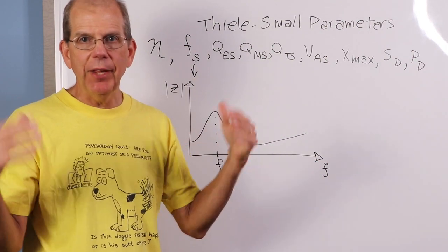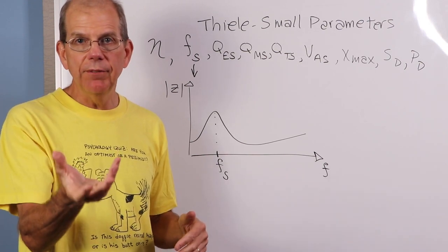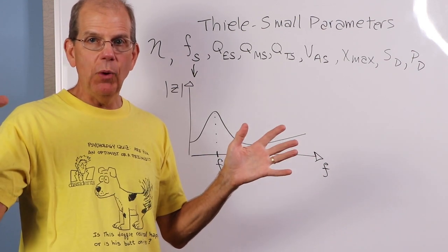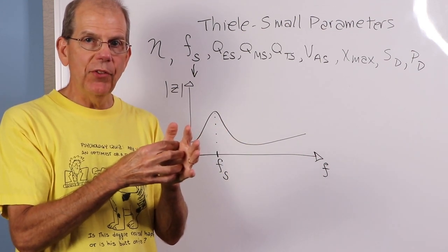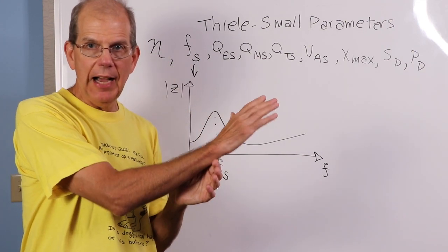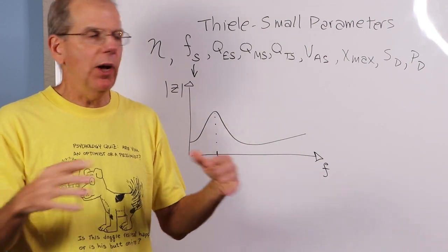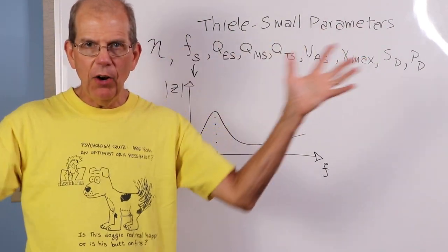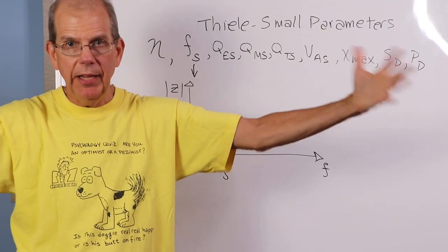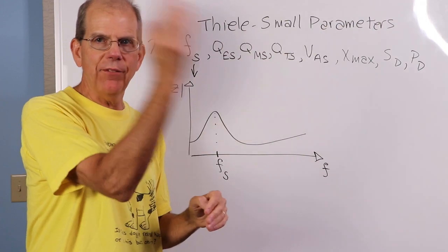So just to use a simple number like 10%. If I have a loudspeaker that's 50 watt rating and it has a 10% efficiency, then we're saying 50 electrical watts in will result in 10% of that, or 5 watts out, 5 acoustical watts out. Okay? How is this different from sensitivity? Well, this measures the entire output all around the loudspeaker, right? It's basically everything. This is what we have available to us. Sensitivity is strictly on axis. It's what's right in front of the loudspeaker.